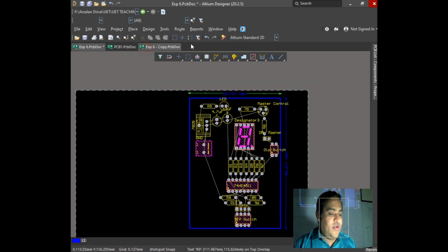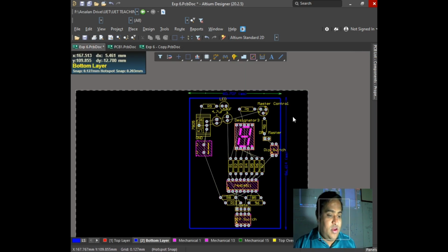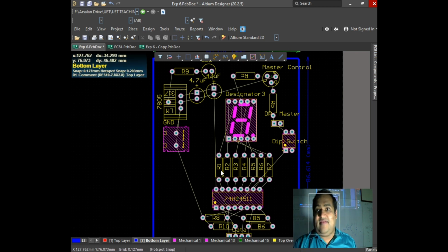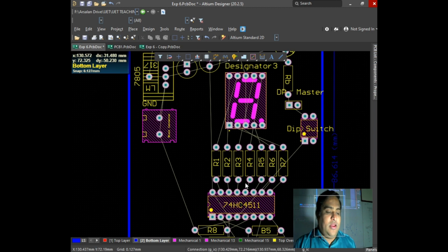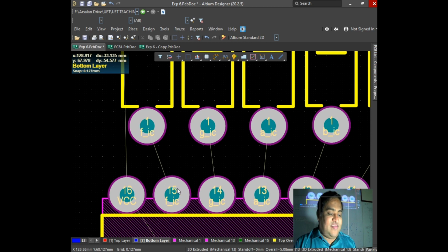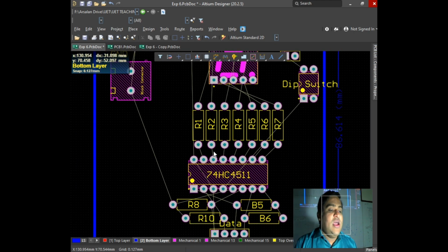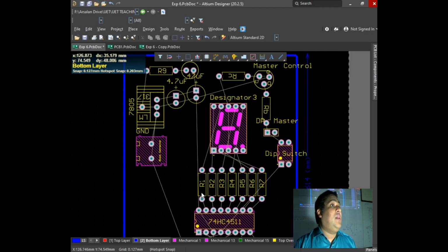If I can open this one, actually not this one. Okay, you can see these white color thin lines. These are actually nets or nodes, and I have told them that they are connected. For example, you can see that this pin number F is connected with this resistor, and there is a fictitious line over there which is telling me that. We are just going to show that on your file as well. So this is something which I am actually going to make you do today.